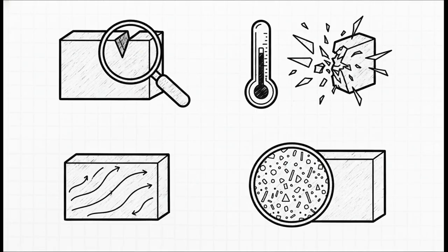Polymer orientation also matters heavily. Because of how polymer chains align during injection molding, impact strength is always higher if you test in the direction of the polymer flow. And, of course, the inclusion of fillers, glass reinforcements, or specific chemical additives will fundamentally alter how the base material absorbs shock.